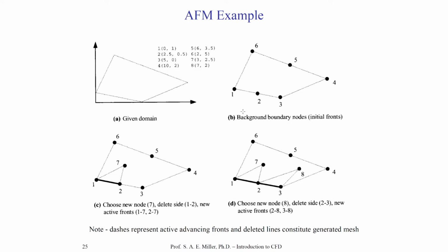Next, we need to discretize the boundary of the domain. We talked about this before. Here, we choose to put 1 node at each corner and then 2 nodes along the connectivity between 2 walls. We do that just to have more grid points and to have better resolved flow. You'll note that unlike the previous approach, we do not place points within the domain. We only discretize the surface or lines of surfaces first.